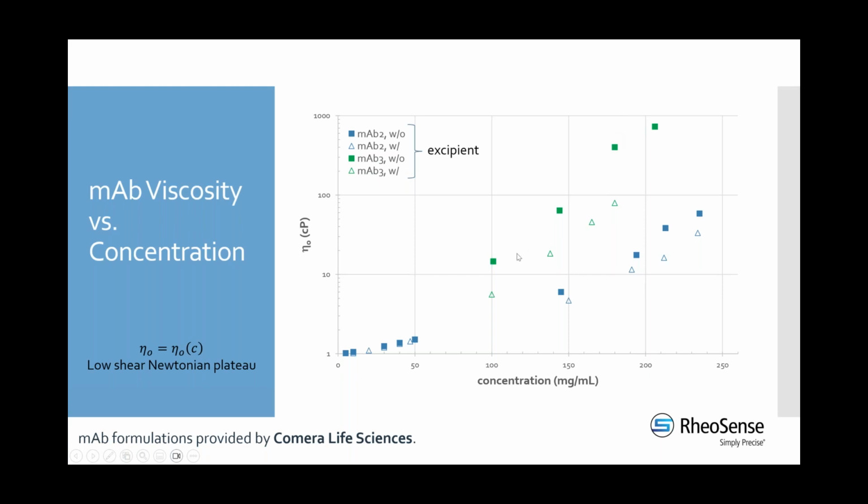The important thing to notice here is that as you get higher and higher concentrations and higher viscosities for these types of materials that we can approximate as colloidal, they interact very strongly. These strong interactions, in addition to Brownian motion of these small molecules, are the type of behavior that leads to shear thinning.